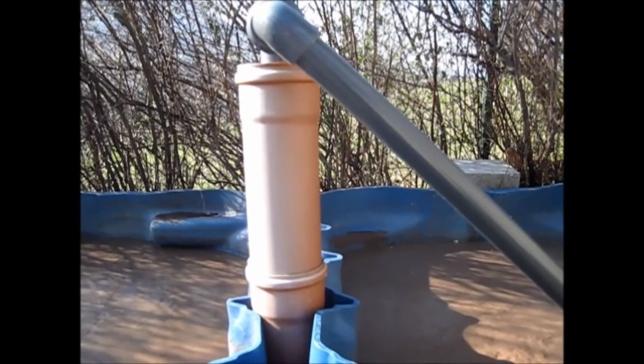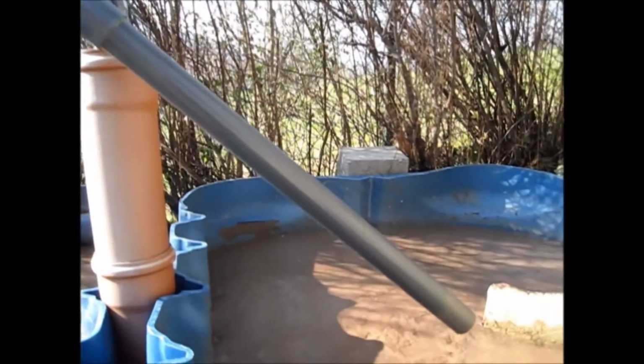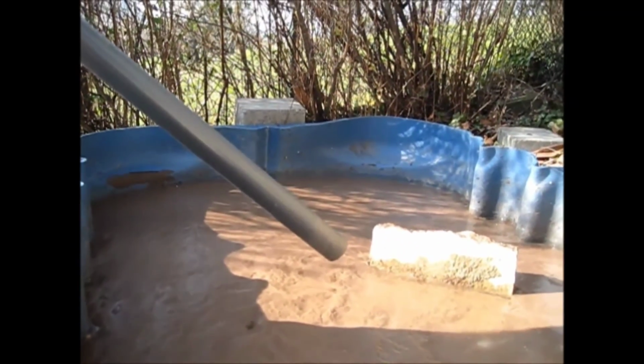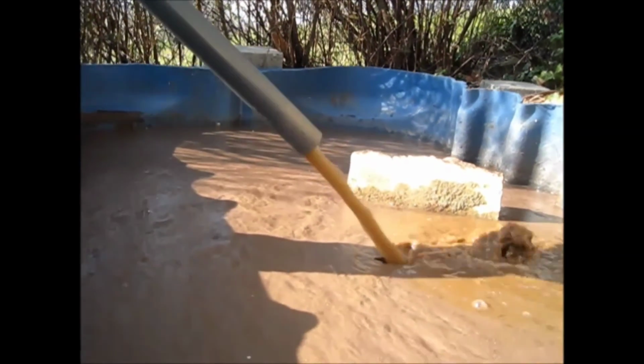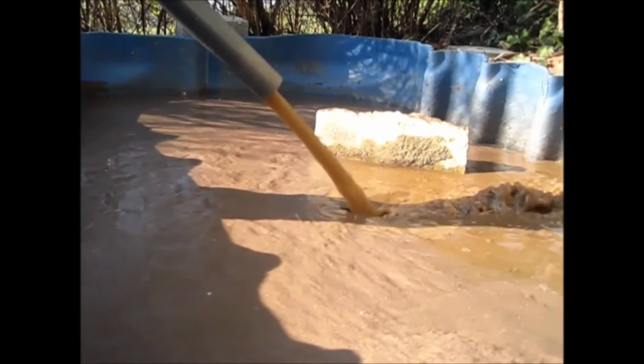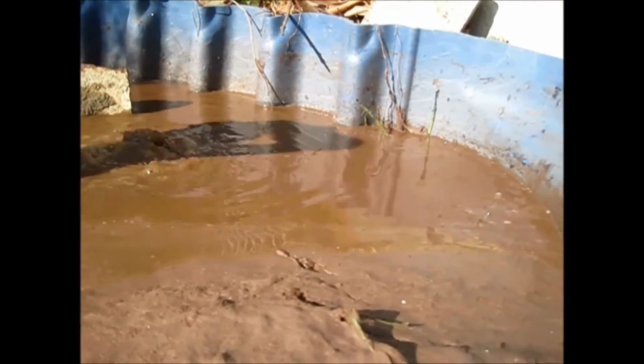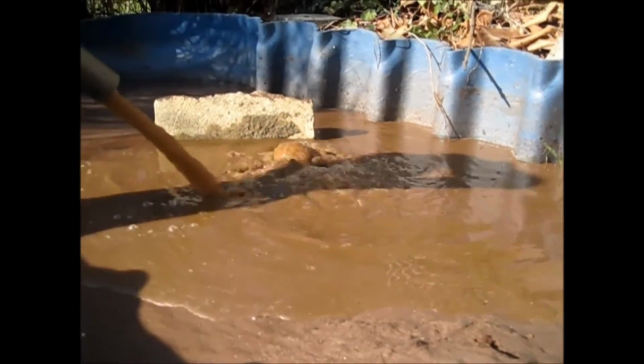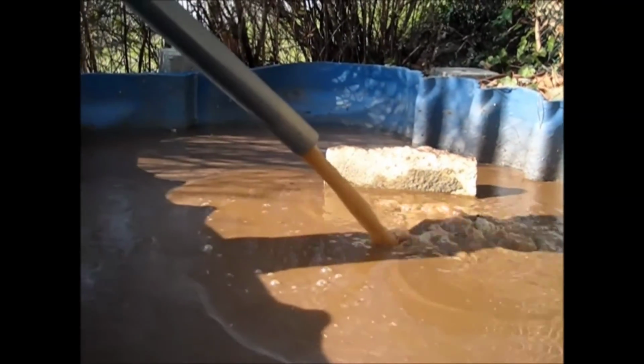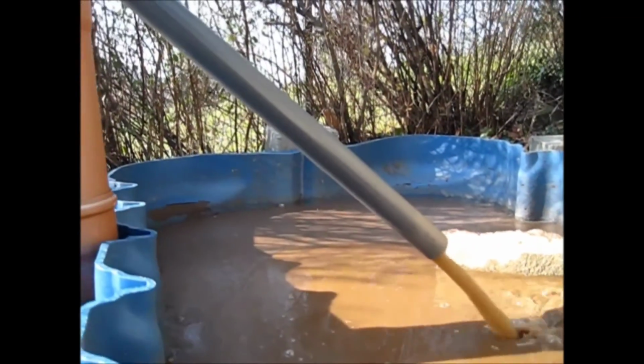If too much sludge is in the system, this sludge is pumped onto the humification reactor. Here, a submerged pump is pumping the sludge onto the field. The water trickles through the filter and gets back into the wastewater treatment plant. The sludge stays on top and dries by sun radiation.